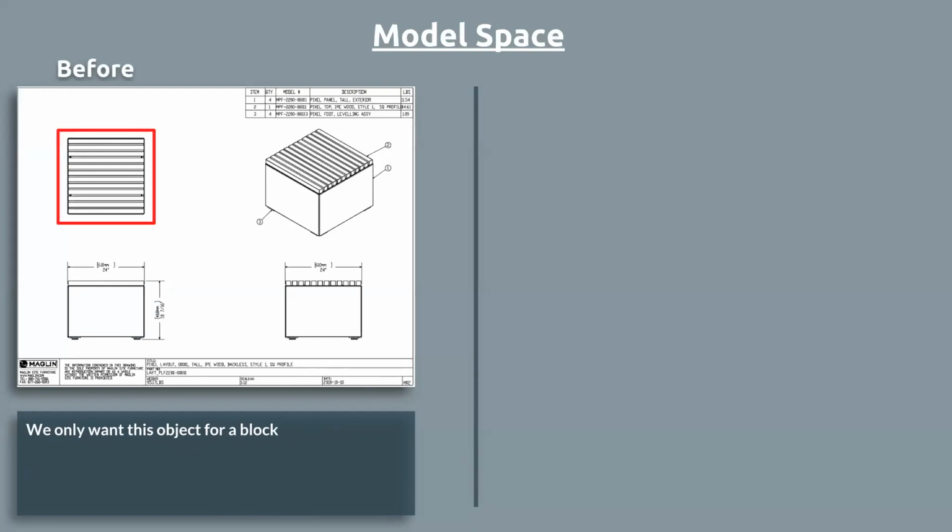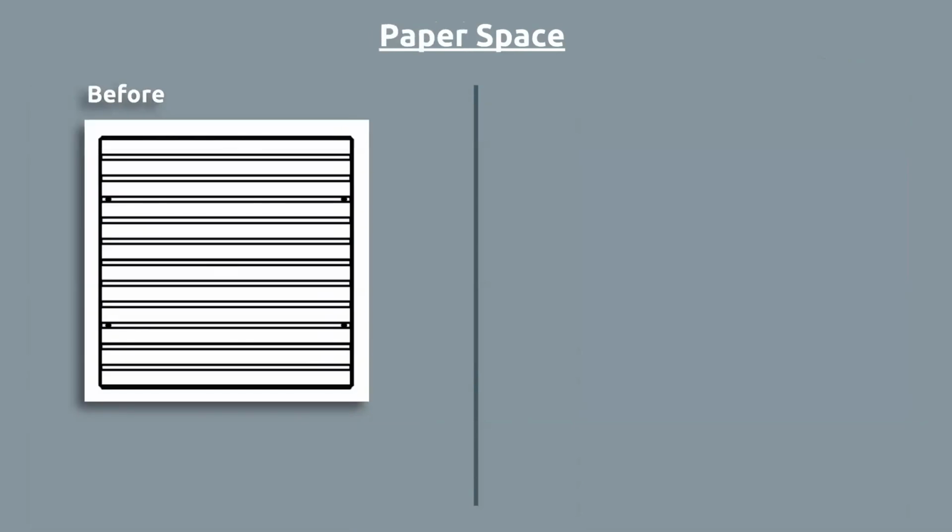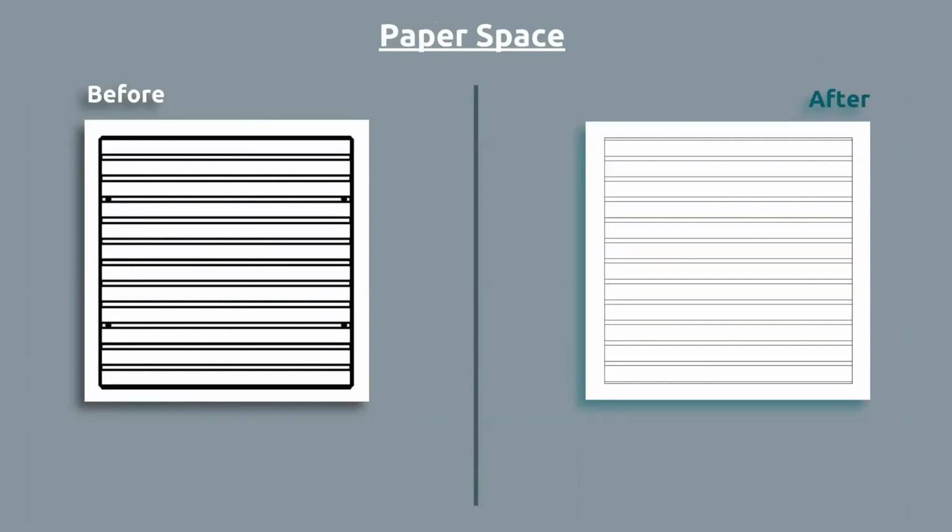Even the part of the resource that we actually want has an immense number of lines. But after all of our work, you'll get something that looks like what is on the right, and just comparing those two basically block properties, you can see that there is an immense difference. And how that block looks on the printed side, in paper space, really makes a big difference when you consider the actual size these are going to be printed on plan, which is way smaller than what I'm actually showing here. But everything needs to be legible and aesthetically pleasing as possible, right? So this stuff really matters. And if you don't want any line work standing out like what's on the left there, again, it's still really, really important.